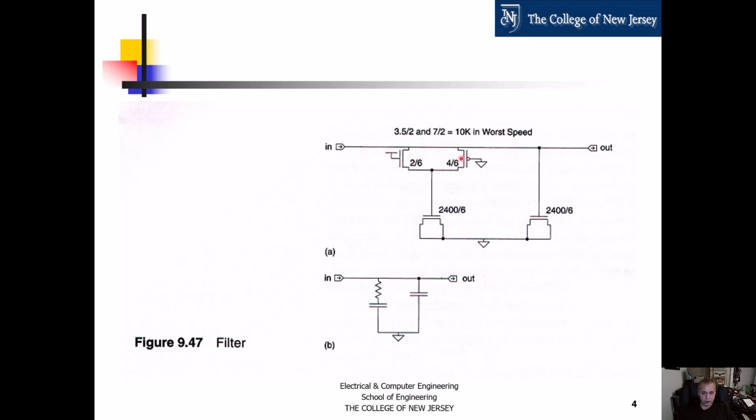They're essentially poor transistors that are resistive in nature with a large RDS on, and they are both on because the gate of the P channel is pulled to ground and the gate of the N channel is pulled to VDD. But the width of the channel is larger than the length of the transistor.